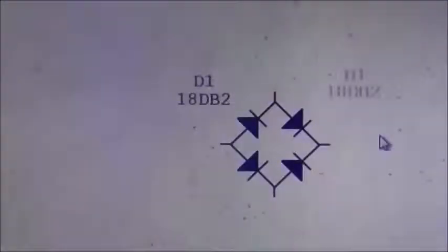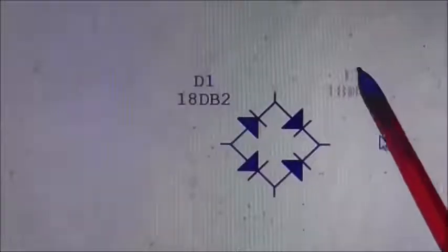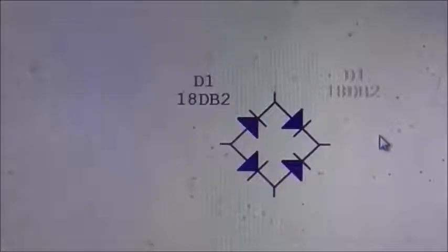Now, it might not be terribly apparent here, but there's a little ghost there, and it's where this text here used to be. And if that happens, what you can do is go to the menu strip at the top, and click on View here. And when that happens, you get options here, and right at the bottom there's Refresh Screen. Click on that, and it clears away all the artifacts.